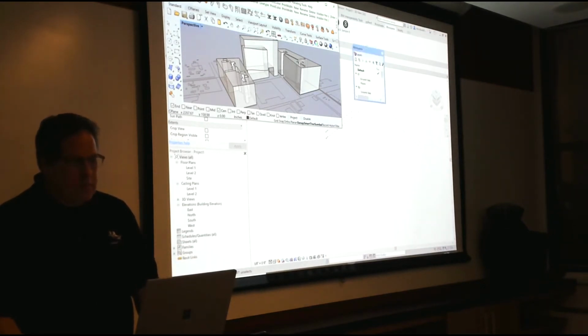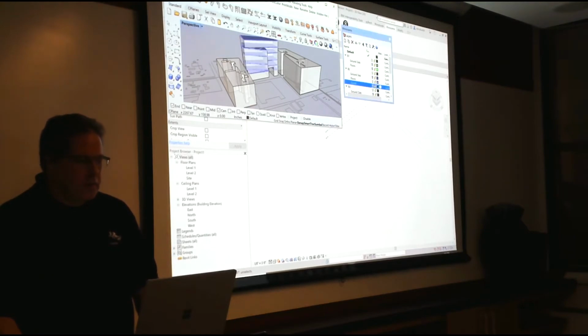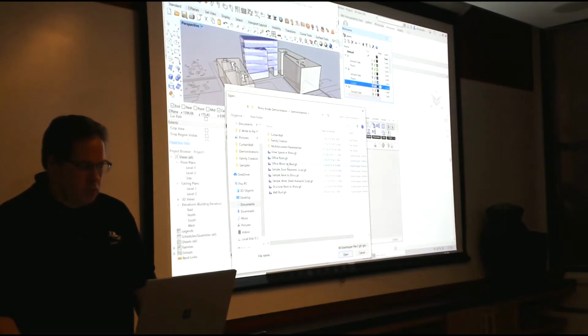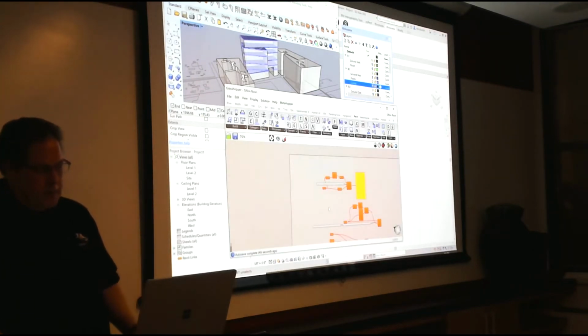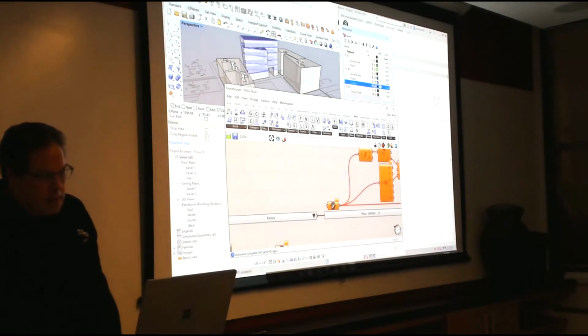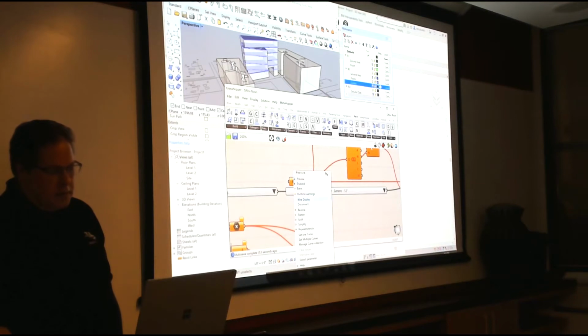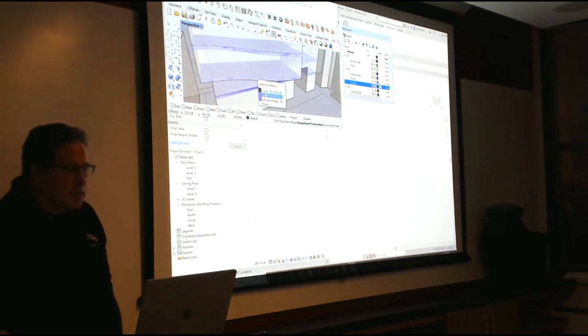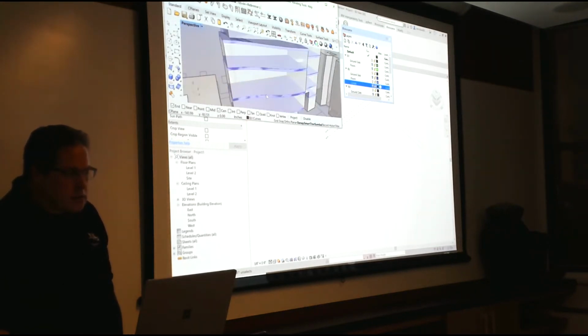So I'm going to open this layer dialog box in Rhino. And I'll open this up here. Okay, and open a little more interesting definition. Okay, so here I have a standard curve picker in Rhino. So I'm just going to say set multiple curves, and I'm going to scroll in here and we're going to pick these curves. Now, one of the things you'll see here is I've named these curves. These curves just have standard Revit names on them, hopefully. So I'm going to press enter here.